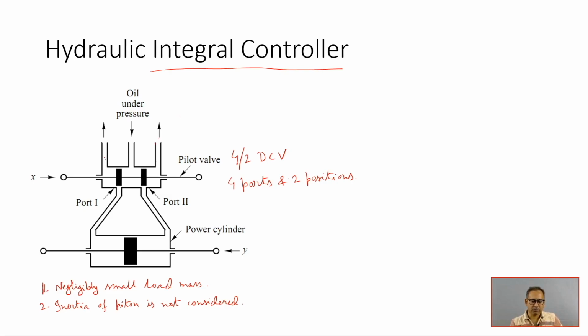So in the hydraulic servo motor, this pilot valve has 2 lands on the spool. This is called the spool, and see, this is the spool here, and these are 2 lands. This is one land and this is the other land. These are 2 lands on the spool. So if the width of the land, see, this is the width of the land, is smaller than the port of the valve sleeve, see, this is the width of the port of the valve sleeve,